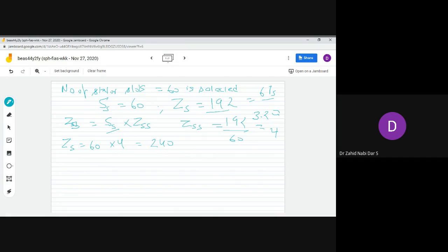But the number of slots will increase dramatically, by 12, and the copper area, the wire, everything will increase, so I have to optimize the cost. So this was the actual number of turns, but this is the optimum number of conductors. Optimum means what I'm actually going to design. So that's why you are seeing that variation.